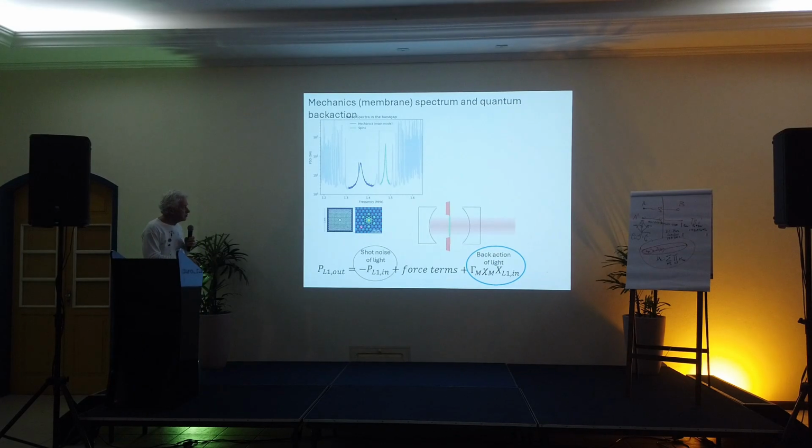So this is the so-called phononic band-gap structure, which only allows certain frequencies to couple from the environment into this thing. What you see here is the spectrum of oscillation of this whole thing, and this is within the band gap. So you see nice and pretty oscillation of this membrane, and outside there's just horrible, don't go there.